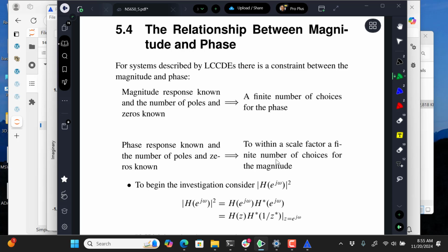At issue is I did a floating point model, they're doing a fixed point model, so that's what has to happen. And it's also a multiplier-less filter. It's a filter that does not require any multiplications or divisions, so that's very nice for the DSP as well. It does just additions and bit shifting. So scaling is done by shifting right.